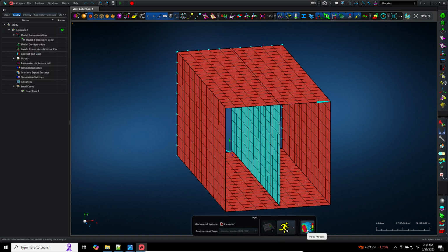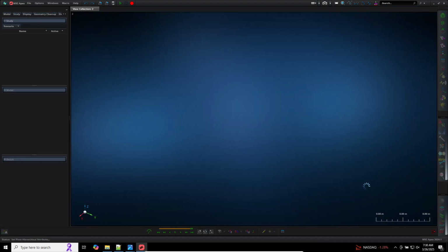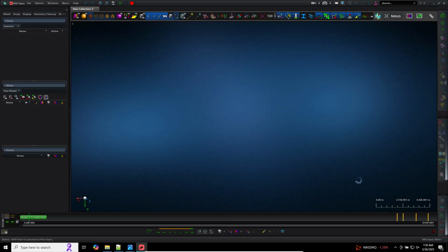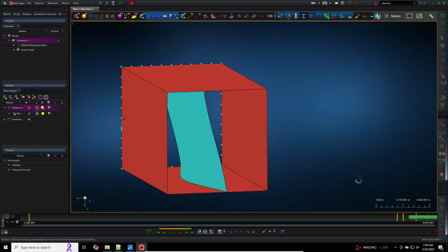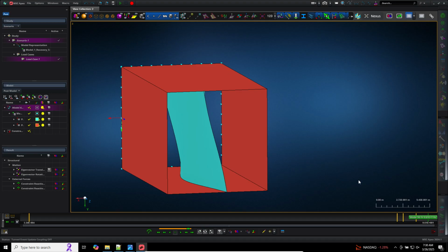Now, there is an engineering purpose for a normal modes analysis. There is also a debugging purpose for normal modes. It's actually useful to identify pieces of the mesh that are not attached to each other. When you open the results, you get multiple mode shapes. Here at this horizontal bar are all the mode shapes, and right now they are being ordered in increasing natural frequency.